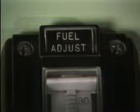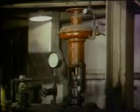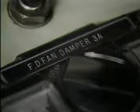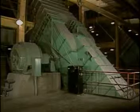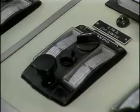For coal-fired boilers, the fuel flow is regulated by adjusting the speed of coal feeders that supply coal to the pulverizers. For oil-fired and gas-fired boilers, fuel flow is controlled by adjusting the positions of valves in the fuel lines. For all three types of boilers, airflow is regulated by positioning vanes or dampers in the air supply lines to or from the forced draft fans, or by regulating the speed of the fans. Changing either the fuel flow or the airflow changes the fuel-air ratio in the boiler.